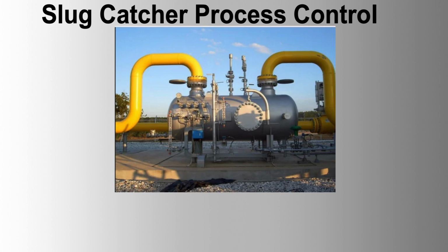3. Cascade control loop for liquid level. Primary loop, level control. Input, liquid level measurements. Output, set point for the flow controller. Secondary loop, flow control. Input, flow rate measurements to the liquid outlet. Output, control signals for the liquid outlet valve.